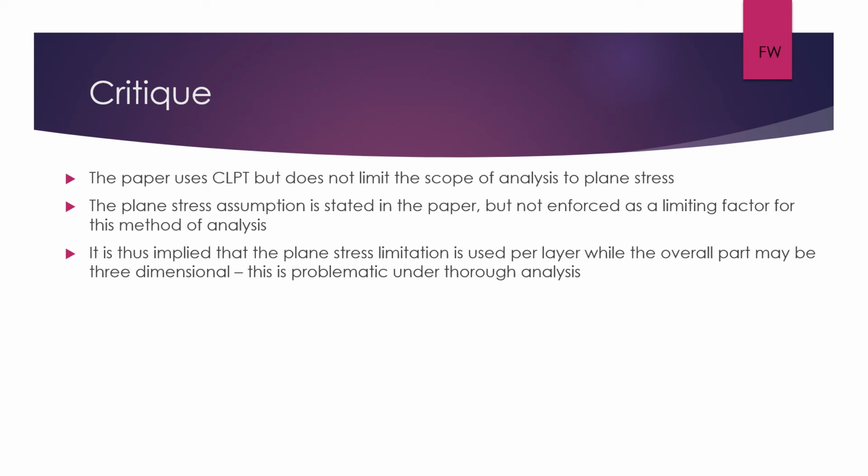It is only referred to in the essence of analyzing one layer. It is then implied, essentially, that the plane stress limitation is used layer by layer, but the overall part may experience some triaxial stress. This raises concerns about the validity of the overall analysis when applied to a complicated part.